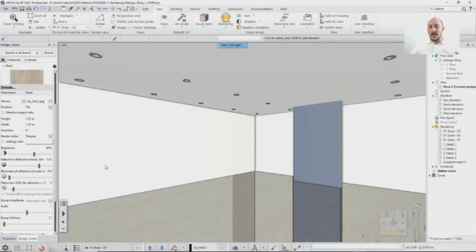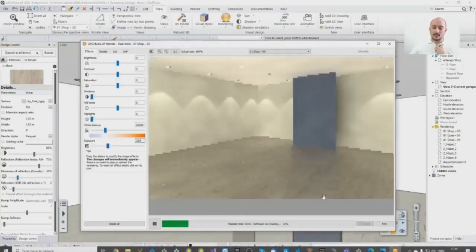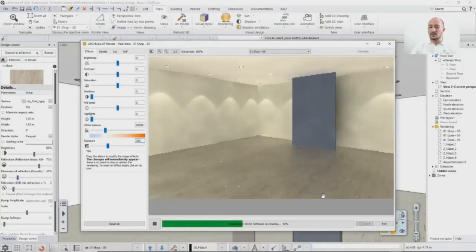But if I would like to have a much more realistic pocket, not a very highly polished version, in that case I just dial this up to somewhere around perhaps 20, and I will test the render, and I see the result is okay. I think this is much better. It has its own glossiness, kind of blurred glossiness, but I like that. I will keep this, and later I can still tweak it.